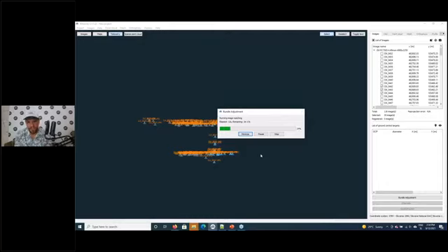So the image matching is taking the longest because all the images are actually pointing on the same thing. So we are actually matching all the 35 images amongst themselves. And now we will just let this one finish with bundle adjustment. And then we will use the results from this bundle adjustment when we do the bundle adjustment on the whole set of images. Let's just wait a minute more for this to finish.